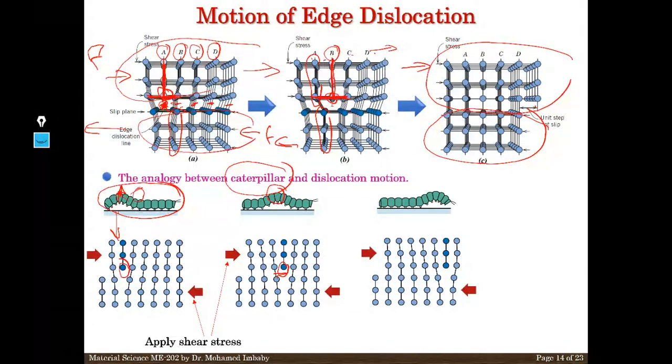In order to make the material move, for example, if you bring a part of the steel and try to stretch it, it will be deformed, right? Yes, and not break, by the way. This deformation happens only if there is a dislocation there. But if there is no dislocation, when you deform it a little bit with the force, it will break, without deformation. You get the point or not?